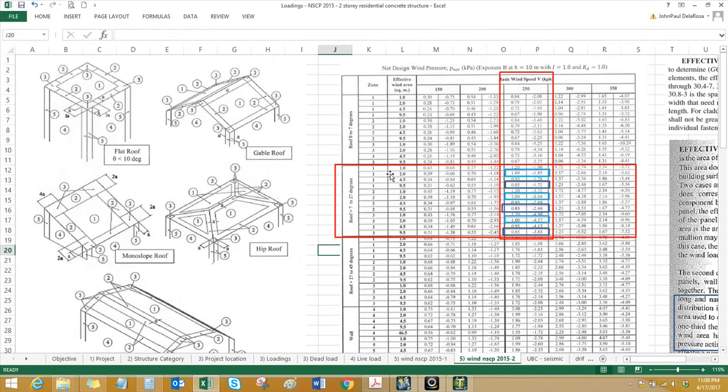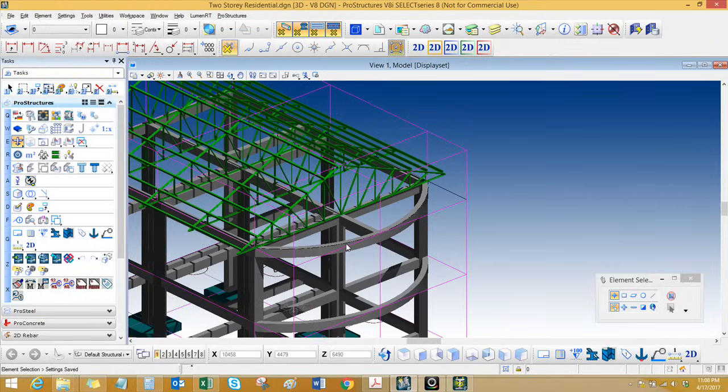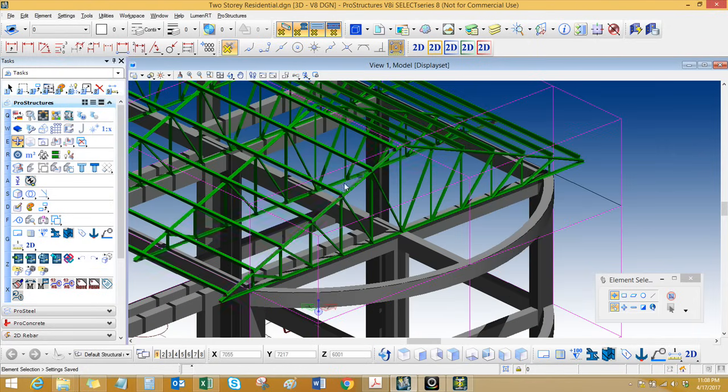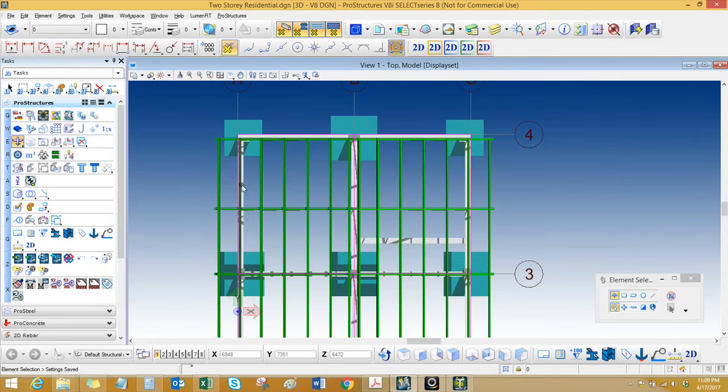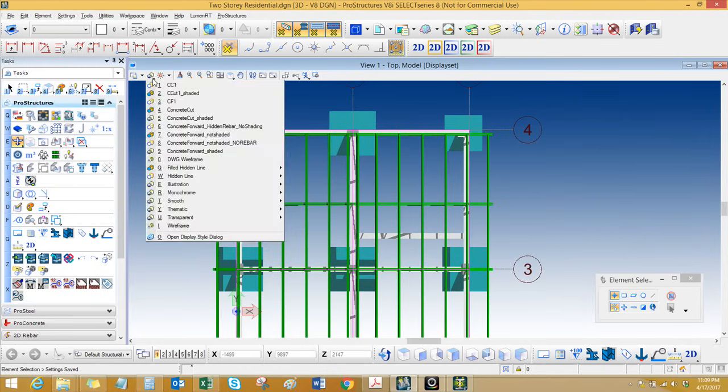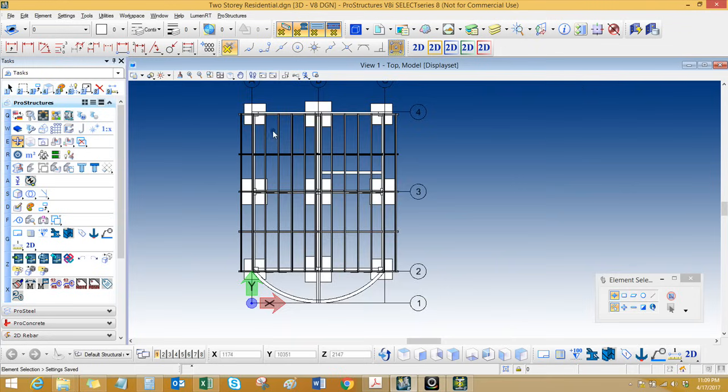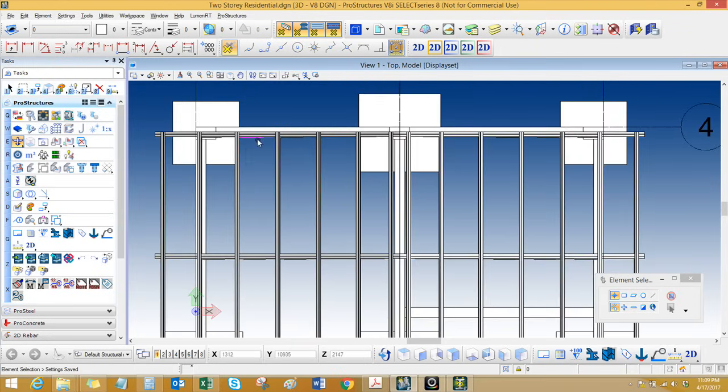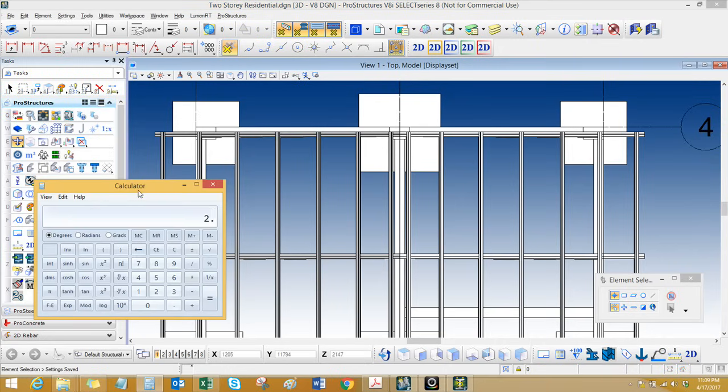Okay? So, yung purlins natin, 0.8, ano, then tsaka 2.5. So, kukunin mo yung i-tab view natin ito. Ayan. So, i-tab view natin yan. Tanggalin siguro natin yung shadow. Okay, so ito yung purlins natin, no? So yung tributary niyan is of course yung spacing din 0.8 then times mo sa 2.5. So, 2.5 times 0.8. Okay?